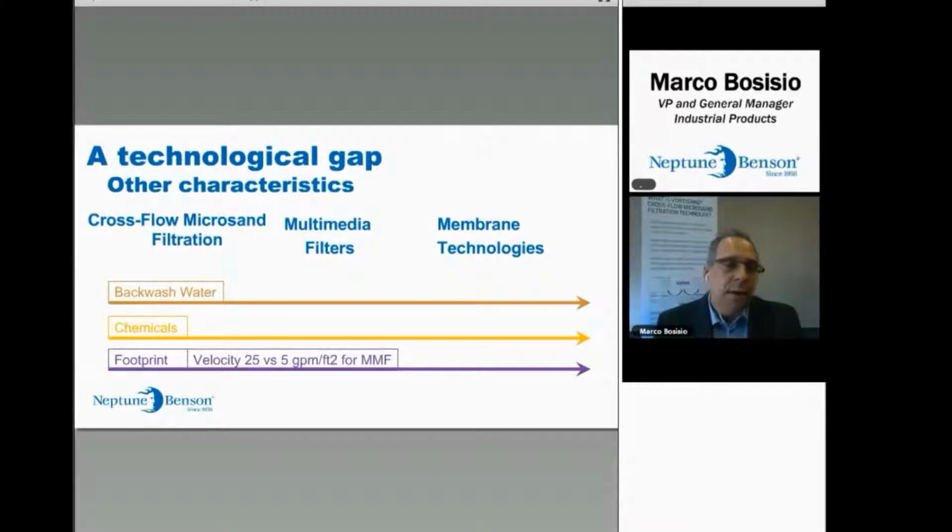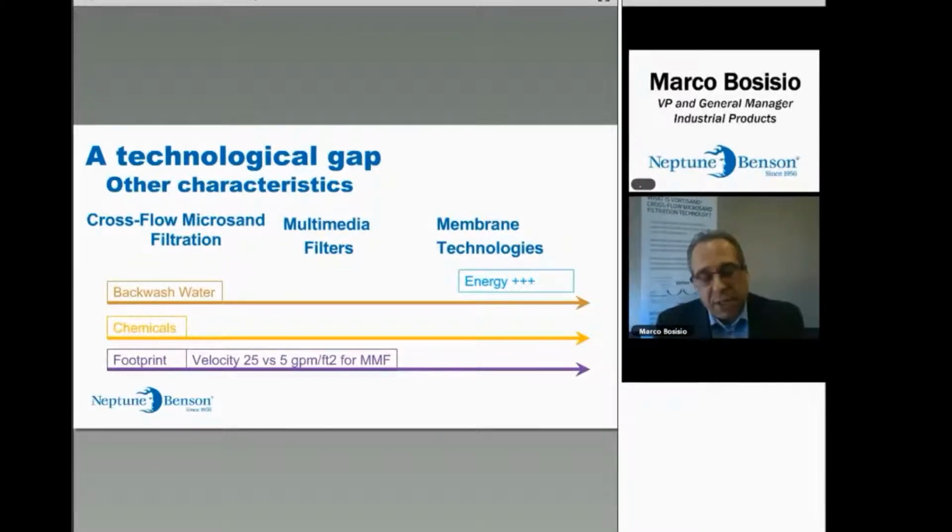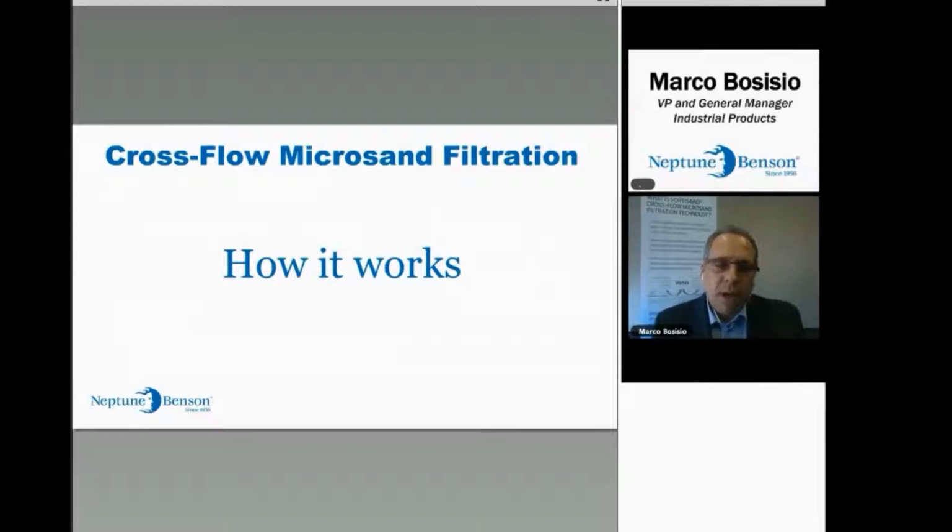And when it comes to energy, it's always a bit different, but everyone will agree that, of course, membrane technologies will require much more energy. Now, to compare membrane technologies to cross-flow is not necessarily fair on the energy side, because it doesn't do necessarily the same thing, especially RO, by which we remove the salts, which is not the case with multimedia filters or the cross-flow. Now, I'm sure the question will come how it works, so let's go ahead and take a look at that.